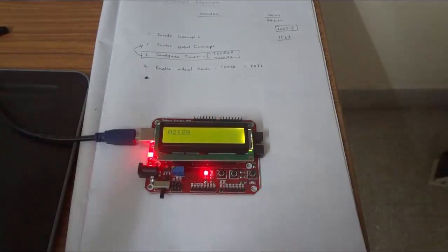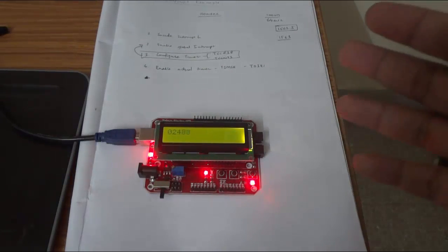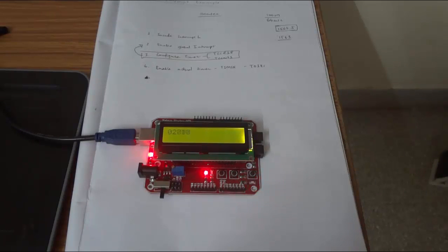You could try some more examples with it, and what I would recommend doing is, in this example we calculated the delay backwards. What I mean by that is, we put a value in the TCNT register, and we waited till it overflowed. This is the perfect case where you could use the OCR register, the output compare register. You put the value in that register, and when the compare happens you could use the appropriate interrupt, the output compare interrupt. That way you need not calculate it backwards, like subtracting the value from 65,536. You could start the timer at 0, and when the compare happens with the value that you need, you can use the appropriate interrupt service routine.